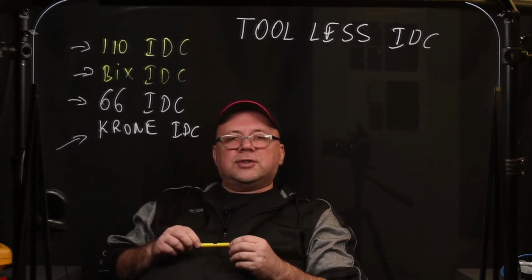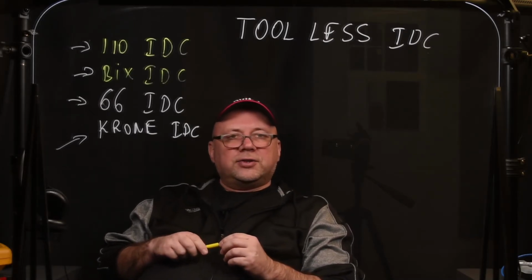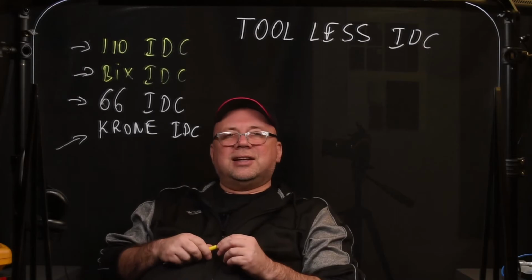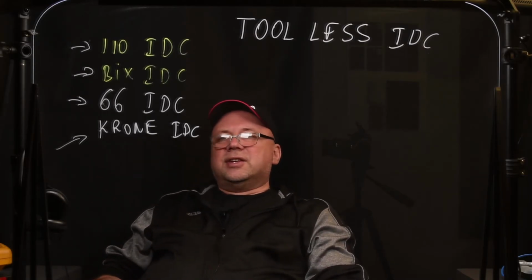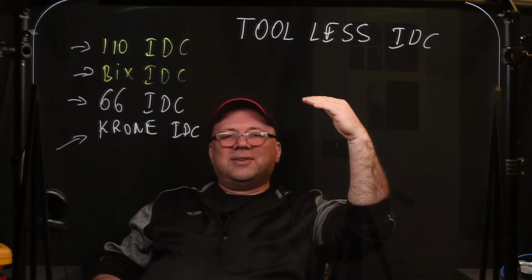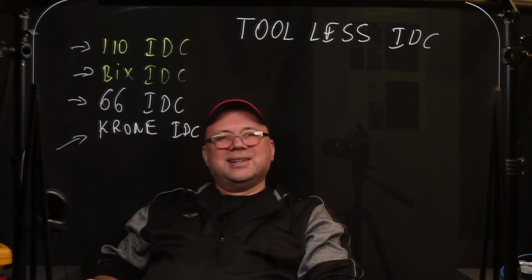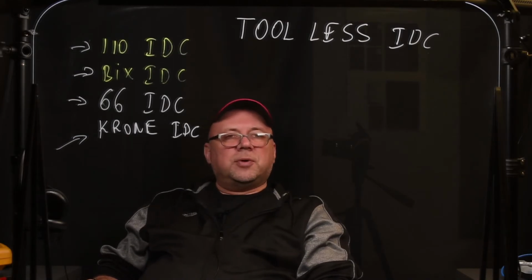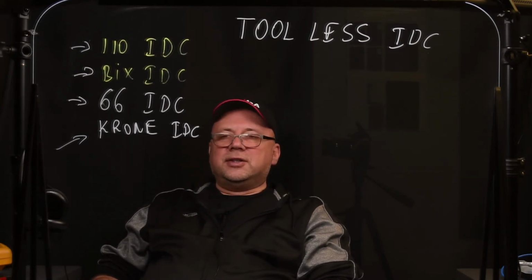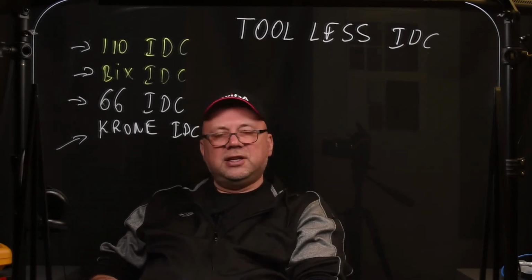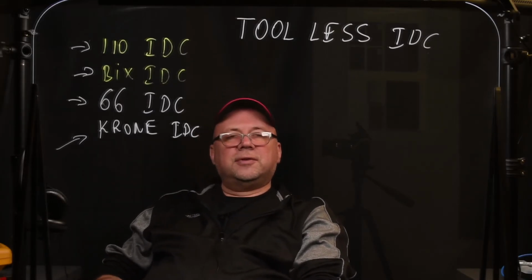Some of the testers are called qualifier testers, so it just qualifies as Cat5e, for example, and it does kind of a lighter duty test. It's going to test for the length, and it's going to perform a little light duty frequency response test, and that's pretty much it. It's going to qualify it as Cat5e, and quite often that's just enough.